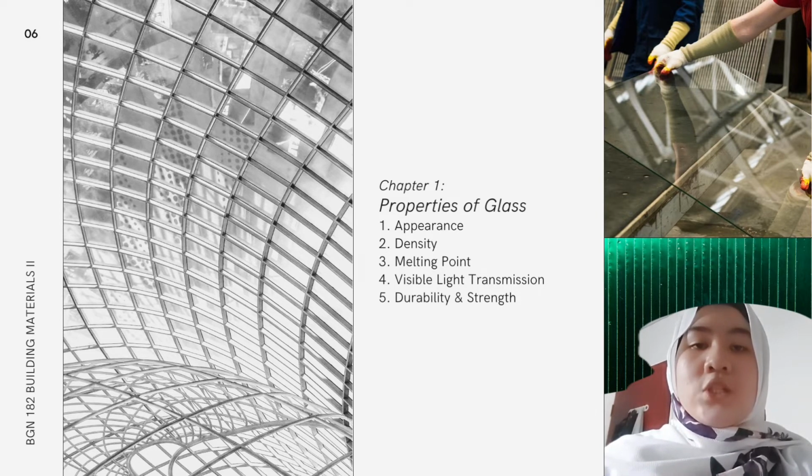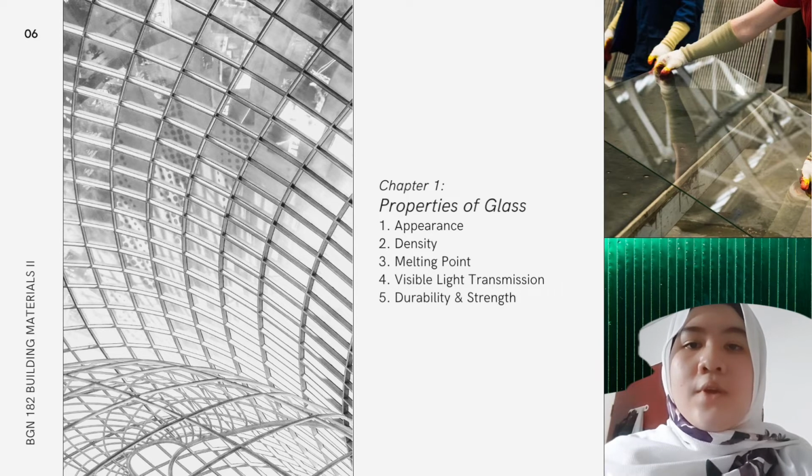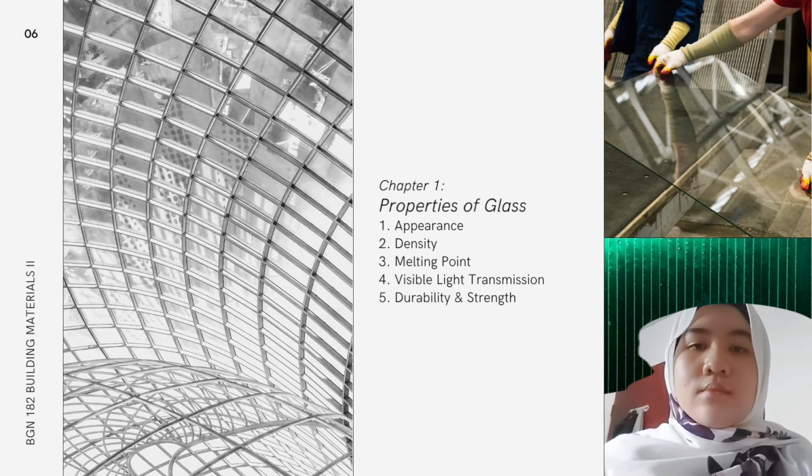Solar heat transmission: ordinary glass is relatively transparent, but solar heat rejecting glasses are available. This transmission includes radiation from the glass itself, which can create a significant amount of heat within the buildings. Ultraviolet transmission: ordinary glass will transmit a very small proportion of the sun's ultraviolet ray. Durability: it's extremely durable in normal condition.